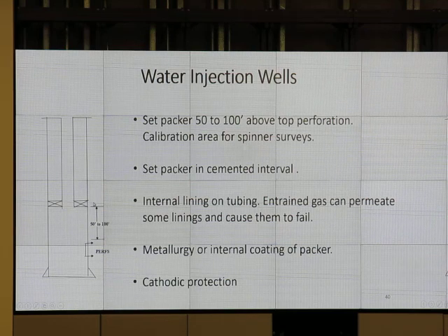The packer needs to be set in part of the cemented interval of the production pipe. Hopefully your production pipe is cemented all the way up, but that packer needs to be set where the pipe is cemented.